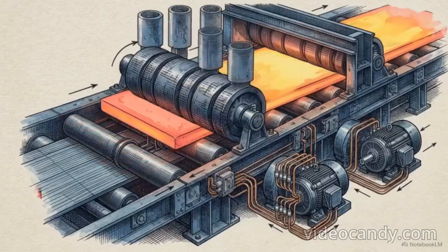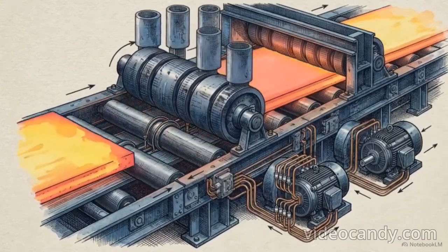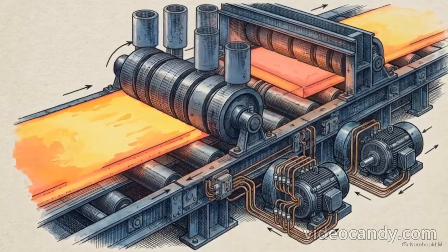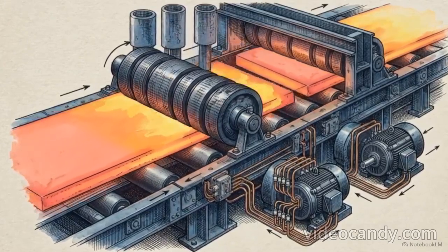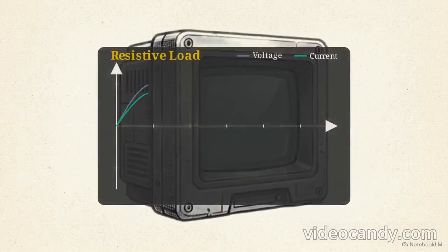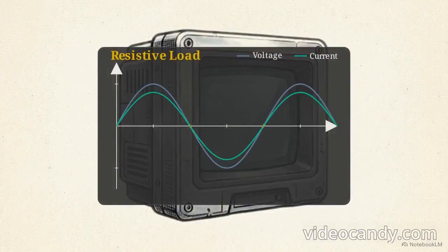By logically passing control back and forth between these two bridges, the system physically weaves a brand new, lower-frequency AC wave directly out of the incoming grid power. That dual bridge sequence is mathematically straightforward, but only if the industrial load is purely resistive. In heavy machinery, that is almost never the case.